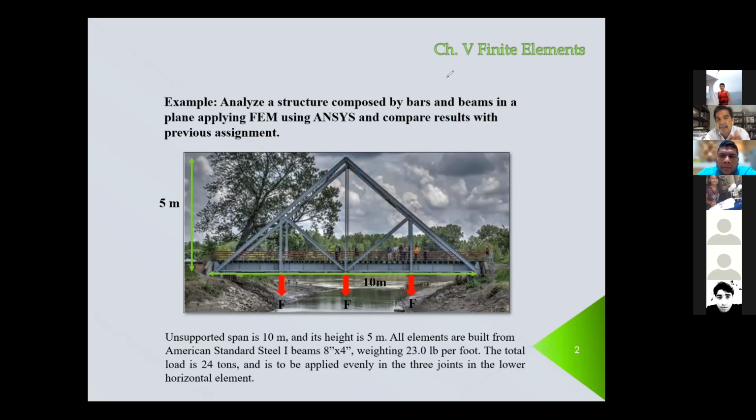That's what Engineer Isaac was explaining. If you assume that support is clamped, put it as clamped. But it is always a good idea to consider the other assumption, that the end is simply supported. So you can take both and analyze the structure. But in the other joints, if there is no support, you just leave them. The loads and the stiffness of the structure will define in what direction they are going to move.